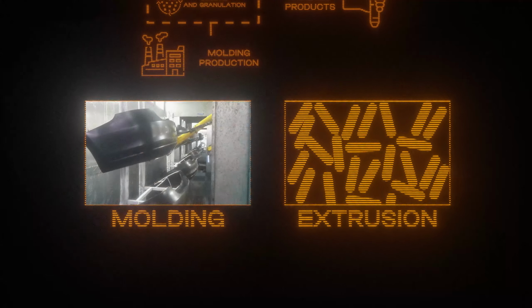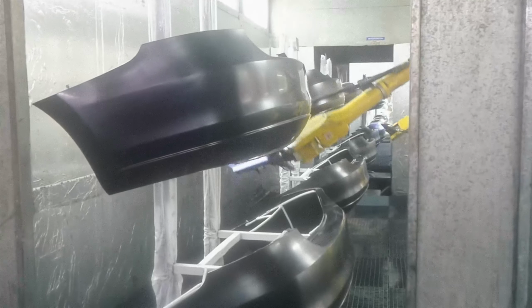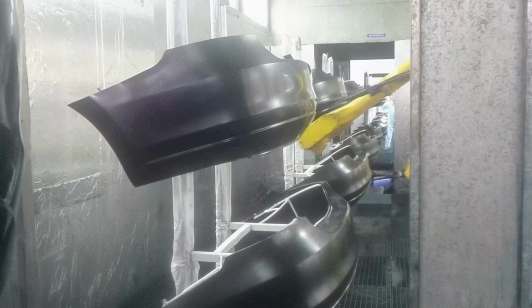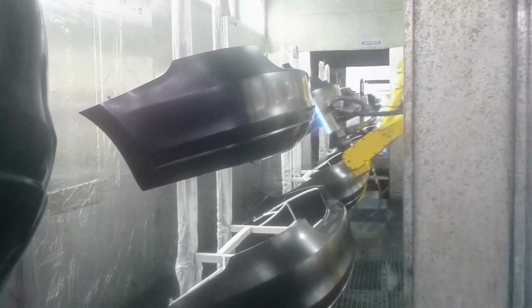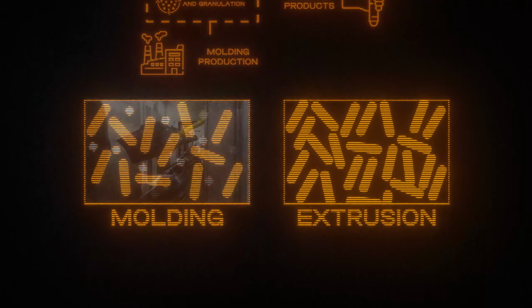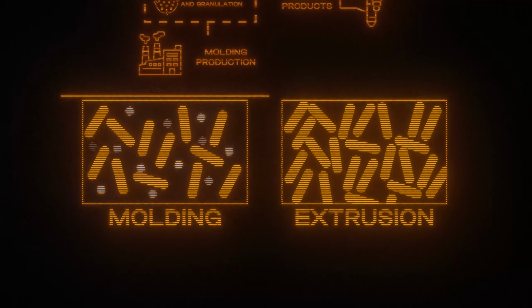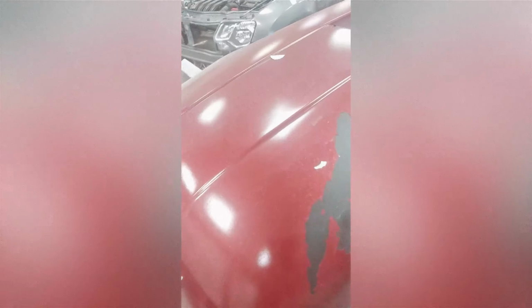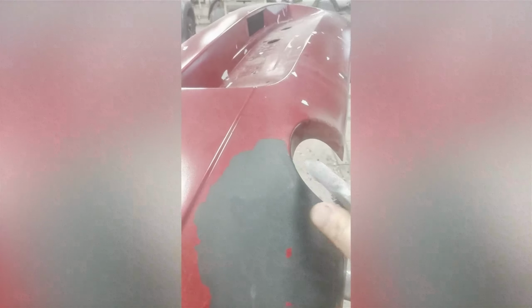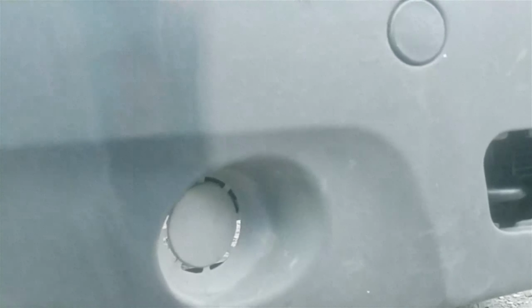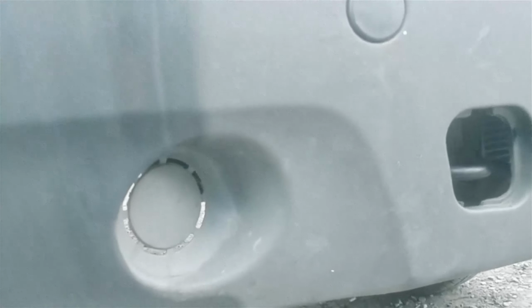Open flame treatment, flaming. The surface is briefly treated with a gas burner flame. The flame oxidizes the plastic surface, creating chemically active groups, OH and COOH, and exposing minerals, which improves paint adhesion. Without this treatment, the paint may peel off due to low adhesion to smooth plastic. Flaming makes the surface rough and chemically active, ensuring the durability of the coating.